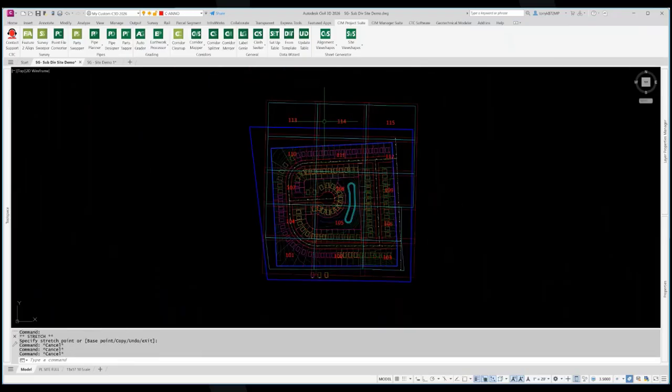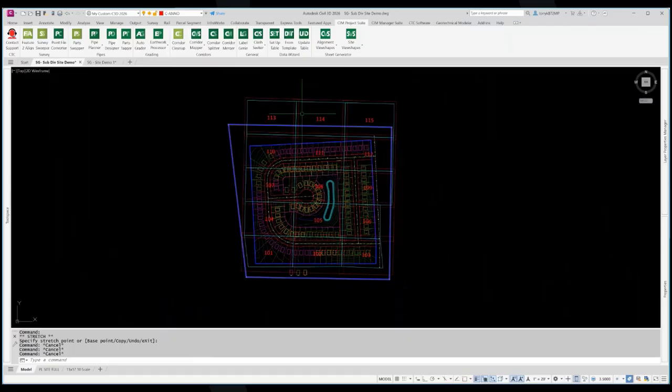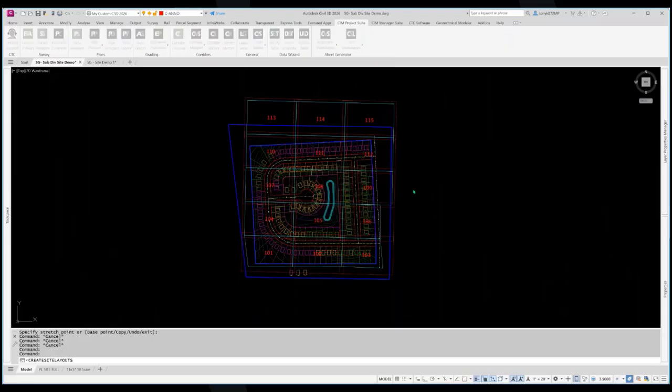I'll show you how to get rid of these, and then we can renumber those as well if we don't like that. These numbers on these blocks come by default as a no plot. They're really just there for you to keep track of your layouts as you go through here. You can renumber these in any form you want. If you want to start up here, you can, but by default it's going to go 1, 2, 3, and then this way, this way, this way. You can change that anytime. I'll show you that here as we go along.